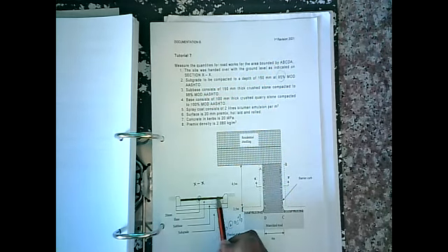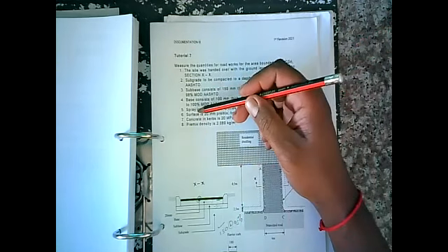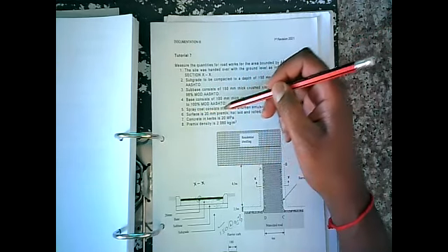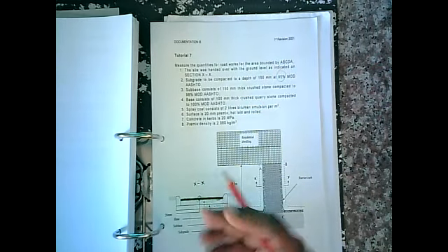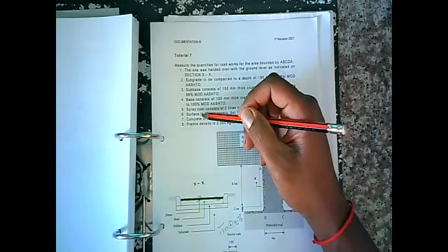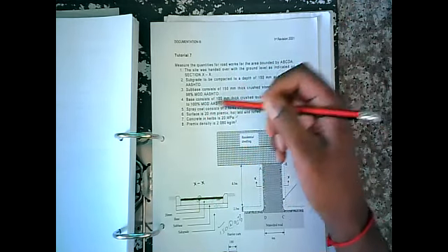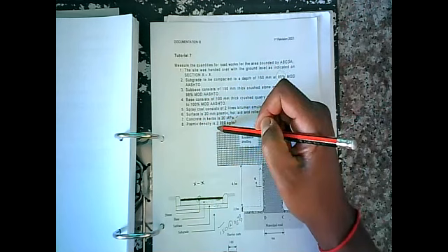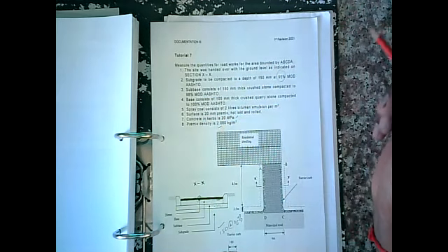So that goes in somewhere there. And the surface is 20 millimeters pre-mixed, hot laid, and rolled. So this dark section is the wearing course, the tar that you're familiar with. Concrete in curbs is 20 MPa. Premix density, as I already mentioned, is 2080 kg per meter cube.